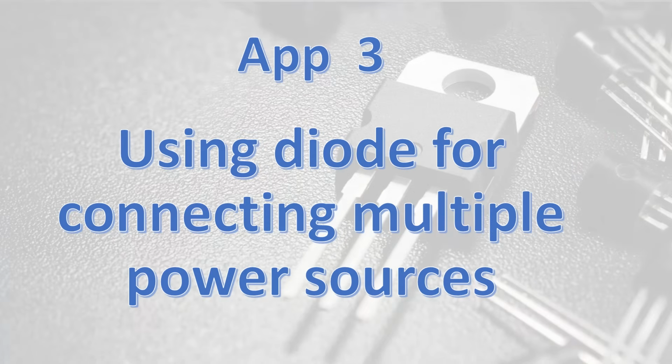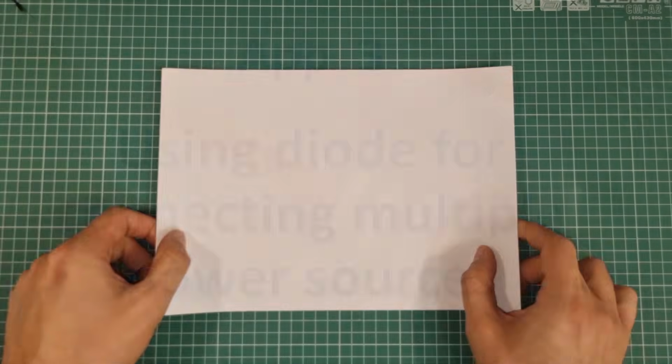Sometimes you need to use a rechargeable backup battery in your project to ensure the device works when power is down. There are many solutions, but using a diode is one of the simplest and cheapest approaches. The third application of diodes in circuits is to connect a battery and power supply together. Application number 3, using diodes to connect multiple power sources.